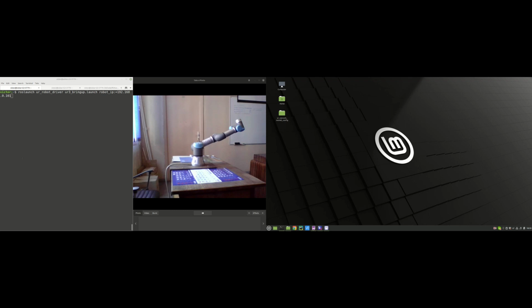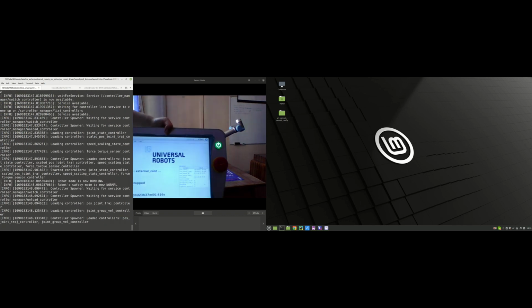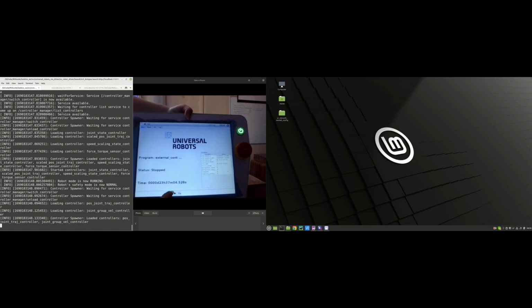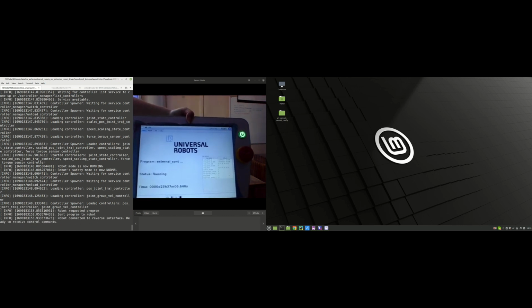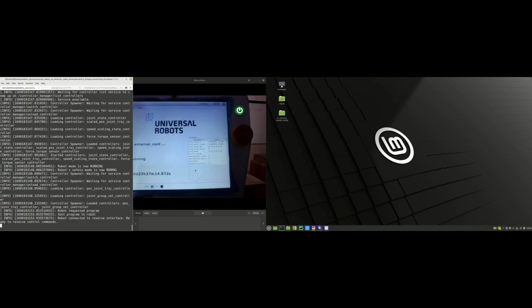Hello! We'll present a short program to show how the robot stops itself in case of collision when we do not set the optimal environment with Moveit. Firstly, we have to set the Ethernet connection with the real robot using UR robot driver ROS package provided by Universal Robots. In order to launch or bring up that launch file, we have to provide the robot IP.